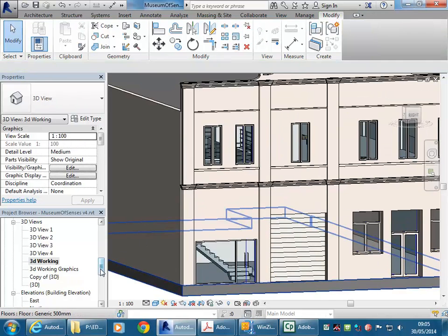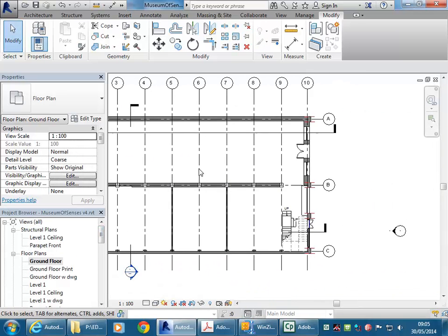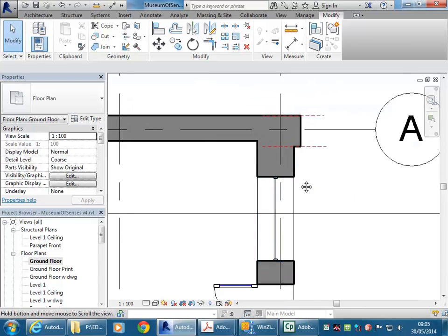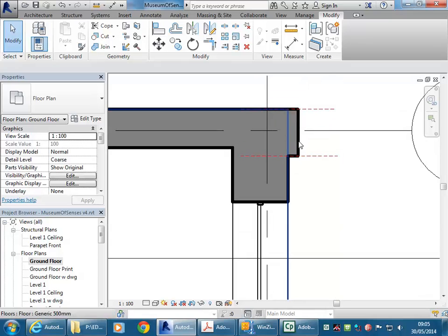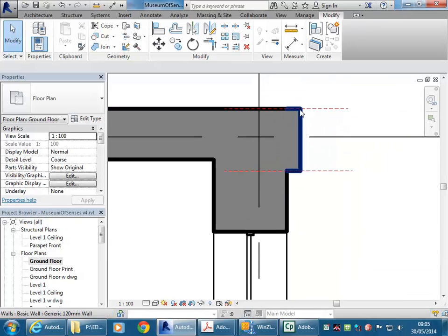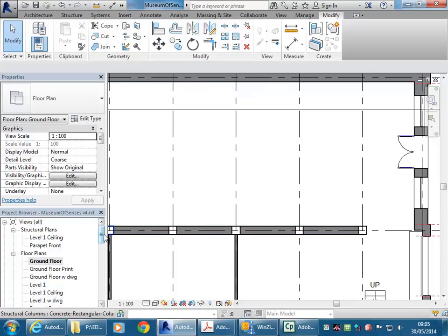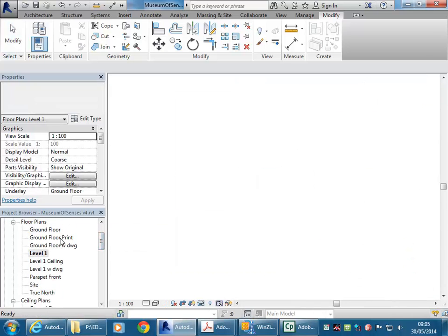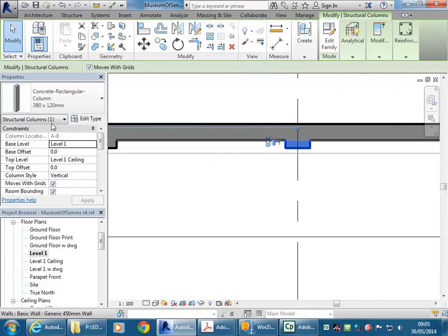And looking in the plan, you can see, as well as the windows and the doors, obviously you can see those, but then we've also got these piers, which I've made in this case using walls. So you might have seen the earlier piers that I did were mostly done using columns. So with the column tool you can make piers, and we use those rectangular columns to do those.